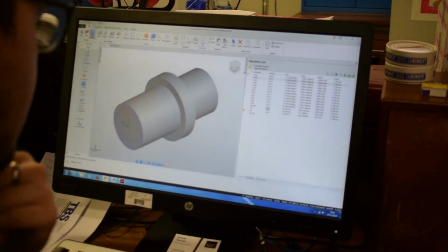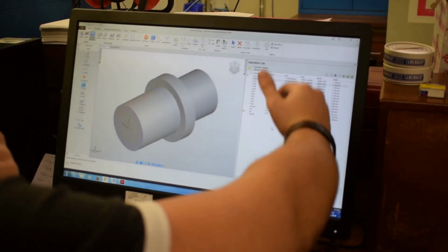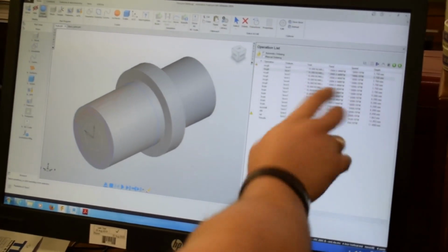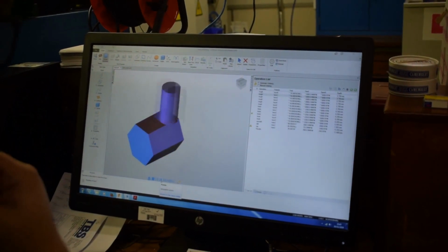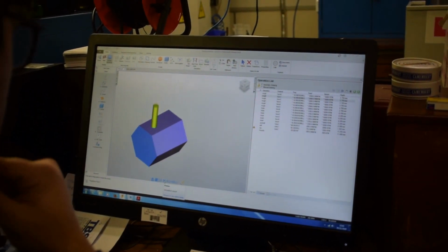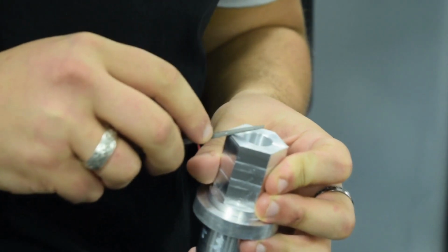The next stage involved using CAD/CAM software to create the correct G-code to mill the cylindrical piece into our hexagonal hub. The hole for the grub screw was also machined here. Again, using a CNC mill here offers a distinct advantage as it increases the rate at which parts are manufactured. Tool changes, for example, are very quick and efficient. Lubricant is required at all stages to keep the aluminium cool. As the tools are moving quickly, friction generated can melt the aluminium and cause build-up on the tool as well as ductile tearing on the surface.